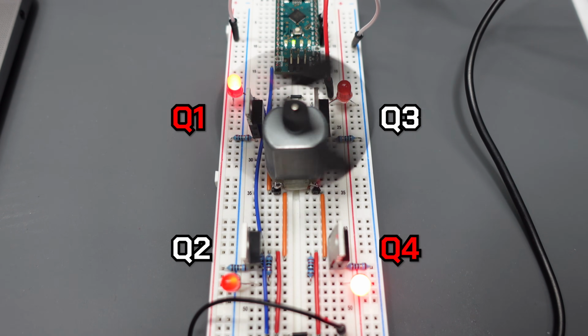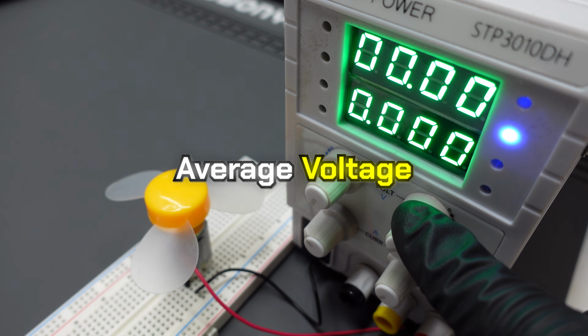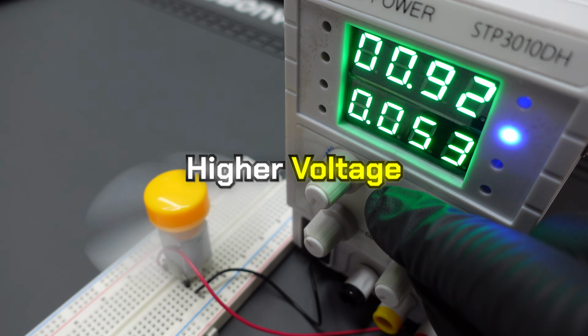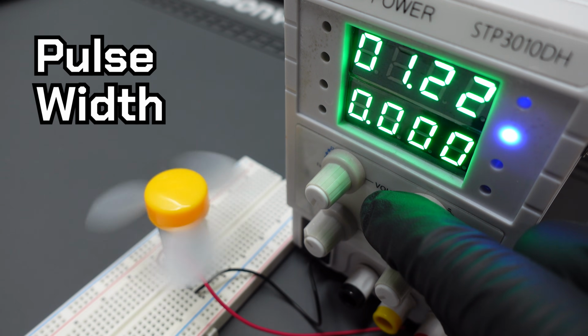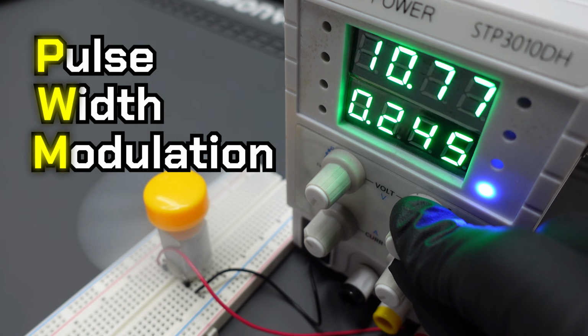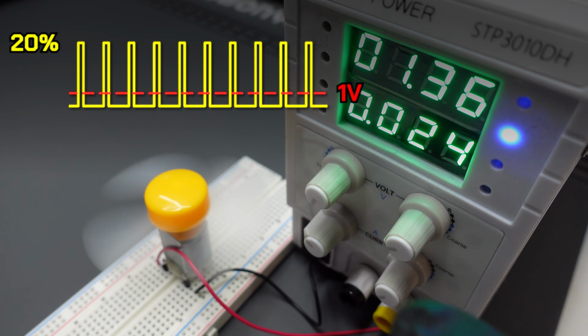Now let's control the speed. The speed of the motor is determined by the average voltage of the motor. So a higher voltage will result in a higher speed. To change the voltage, we use a method called pulse width modulation, or PWM for short. You want to pulse on and off really fast so that it averages out to a lower voltage.